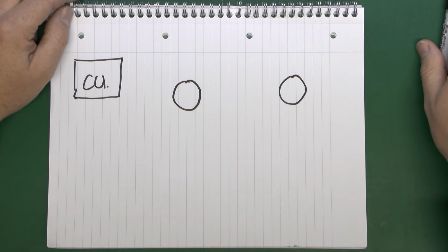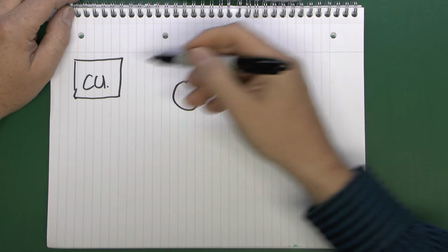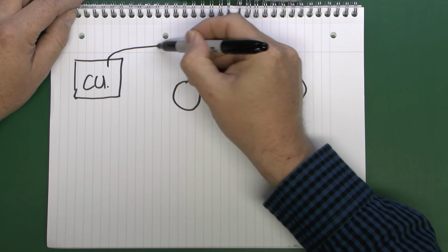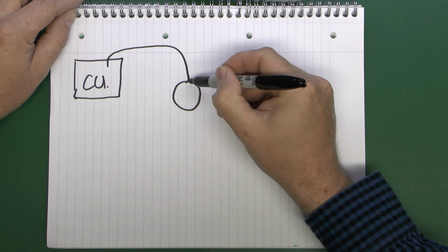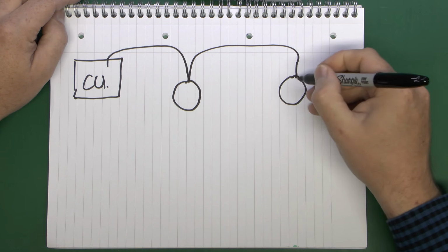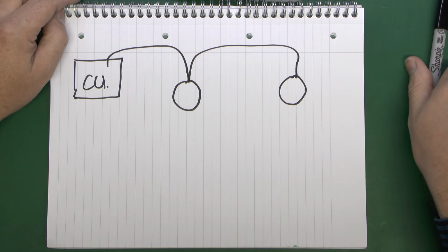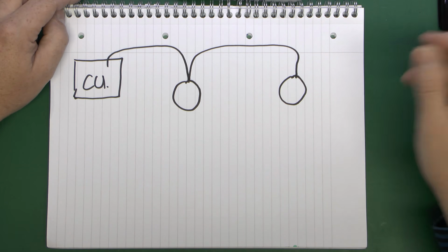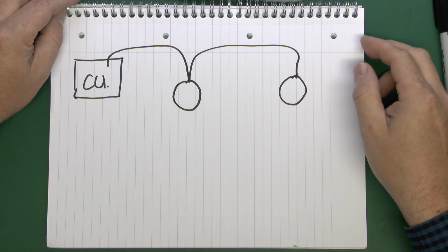In the simplest circumstance, your cable would come from the consumer unit and go into the first light fitting, and then from the first one continue on to the second one. You could continue on to a third and fourth and so on to the rest of the building, and that's pretty much the same as you would have with socket outlets.